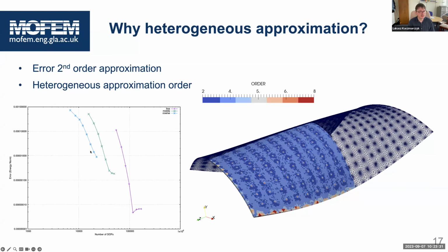So at the end, if you're doing it for different mesh densities, we're getting exponential convergence. Here we hit the bottom level because in that problem we are restricted by the quadrature rule which we can deploy, and we cannot construct a quadrature rule high enough to raise the polynomials above 8.